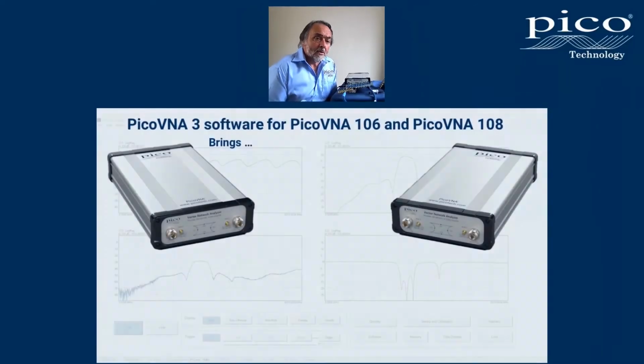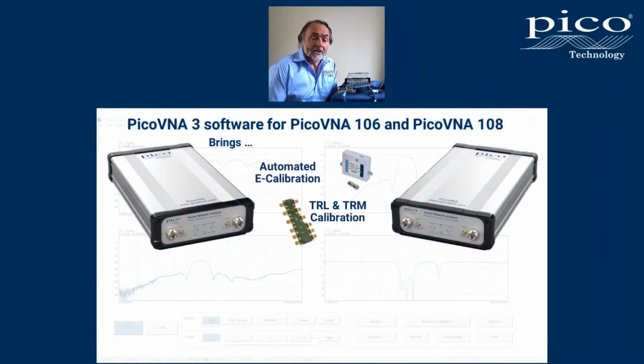Hi, I've got a PicoVNA 108 here, but our latest release of PicoVNA 3 software runs either a PicoVNA 106 or a 108. And in doing that, the 106 now supports automated eCal and TRL, TRM calibrations.